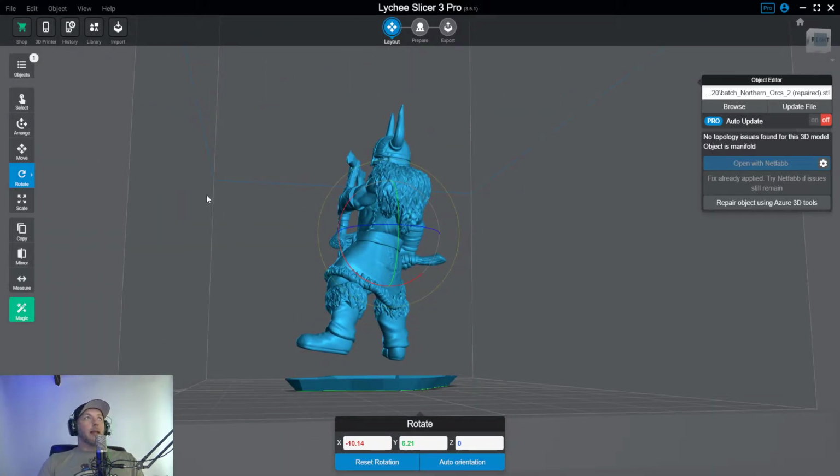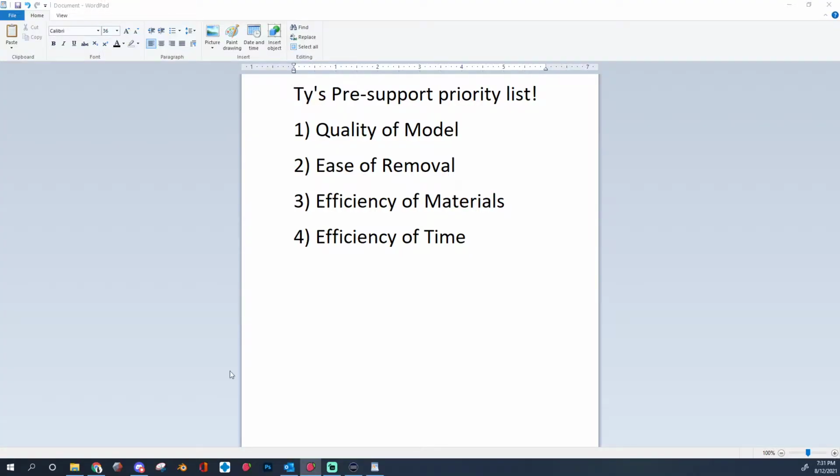Now this print time kind of kills your, you know what? I realize, oh no, we're good. Okay. I thought I had the wrong screen up. So this print time wears down your consumable parts in your printer, right? Your FEP is consumable. I don't think it takes damage, but it wears down over time. Your screen is consumable. Your LED lights are consumable. They will all give way eventually, right?